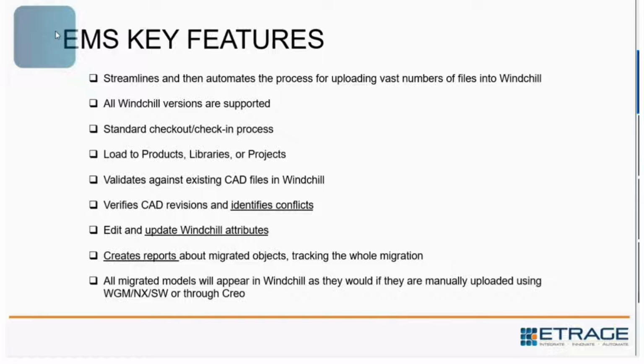There's a lot of pre-migration effort put into this. We want to make sure we validate against any existing CAD files in Windchill. We want to verify CAD revisions, identify conflicts. We want to clean up any Windchill attributes before we do the migration. And you're able to create reports as we go, so you're able to track the whole migration. And in the end, it'll be as if all these files were manually uploaded into Windchill.